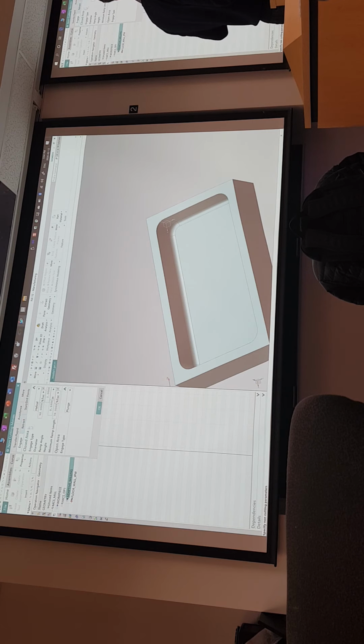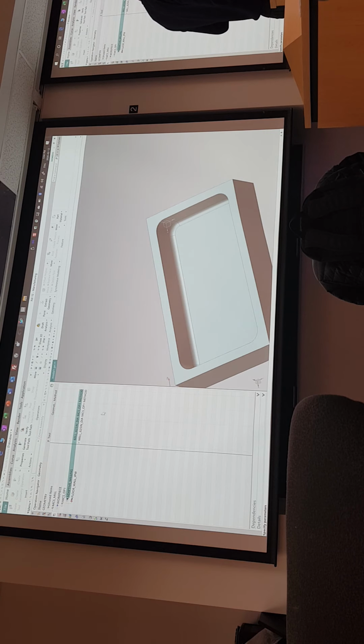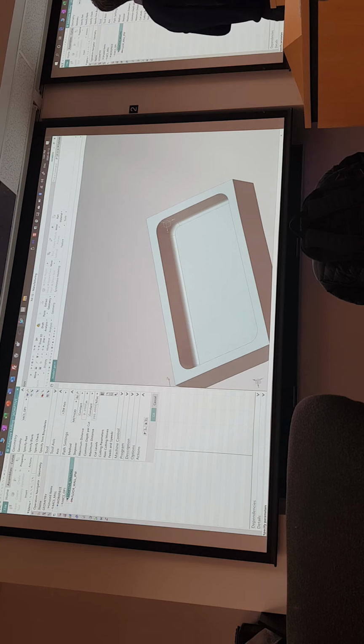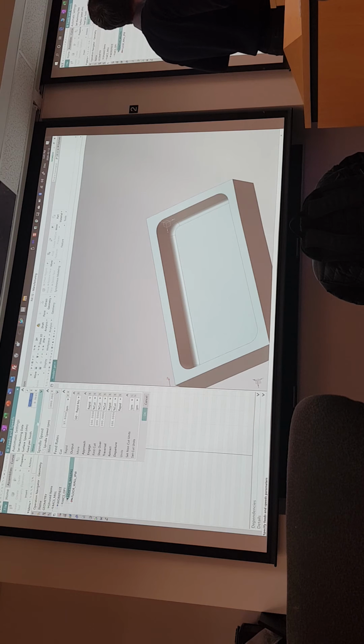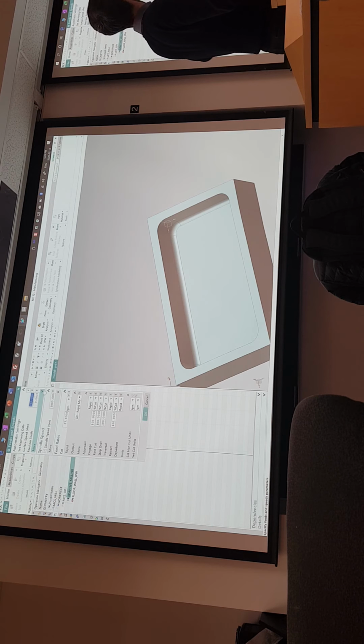So here you can set your approach in the closed area, and also your retract, along with many other types of options. And then for feeds and speeds, I mentioned that you can back calculate each one, so you can fill in any single one of these.